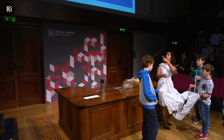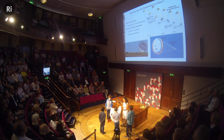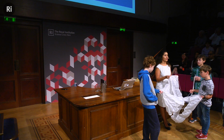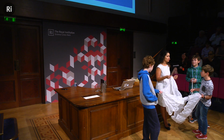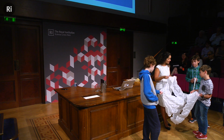It's huge. And so you can see from the picture there the size of the people, the size of the parachute. And the reason why the parachute has to be so big is because the atmosphere is so thin, which means a bigger drag area so that you can slow yourself down. And the reason why we like a lightweight device is because when you go into space, you usually don't have a lot of mass available to you, right? Otherwise, more mass, more propellant. So you want something which is as light as possible.